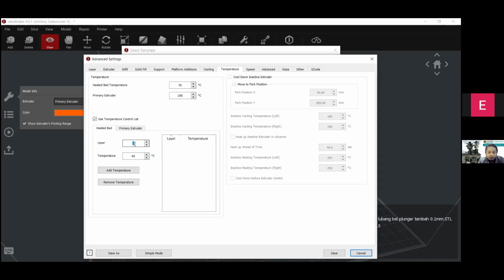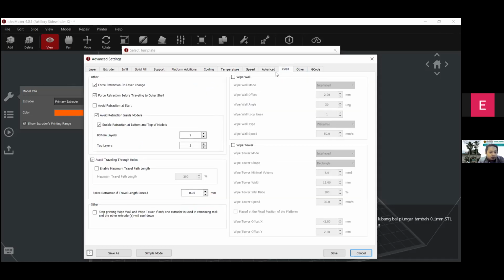So it can just pop up from your heated bed after all the printing process is finished. All right, and overall the speed advance, the ooze is also one of the issues in FDM. So we need to control that. We have to actually try and error this one. You have to experience that. We know that different materials also pose different ooze settings sometimes. So yeah, retraction, all the things you have to consider as well.